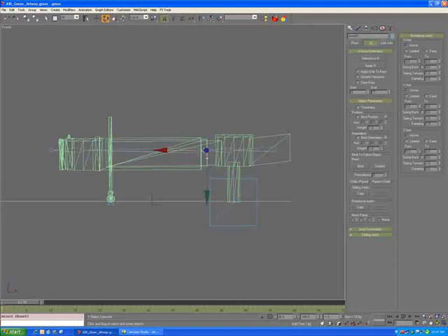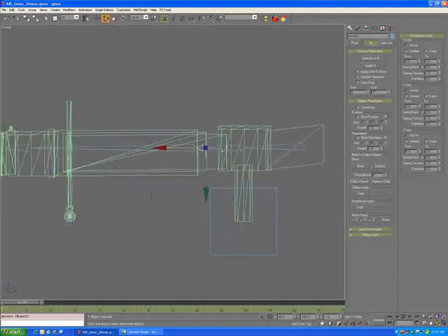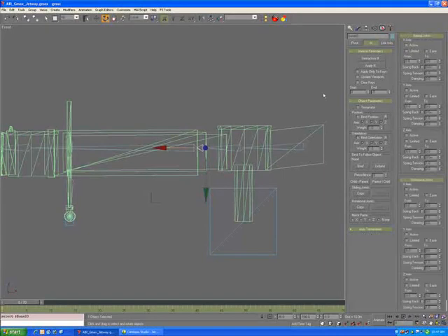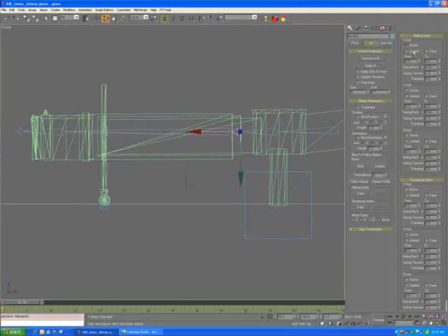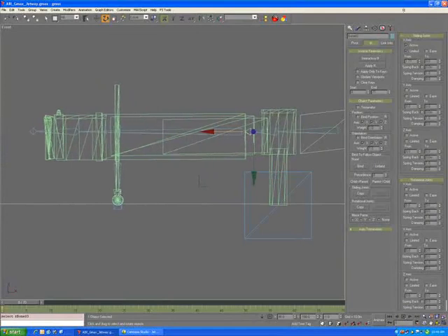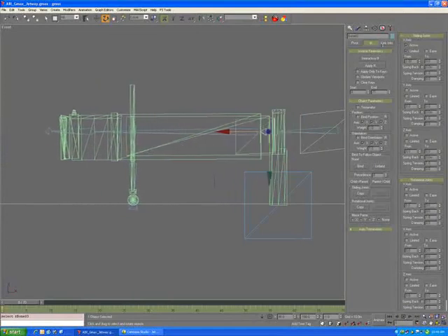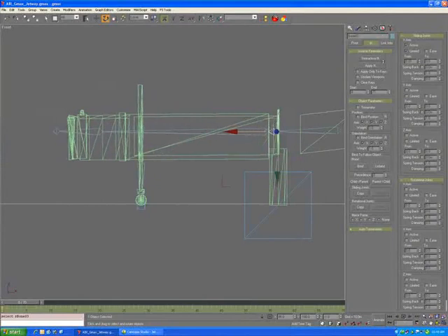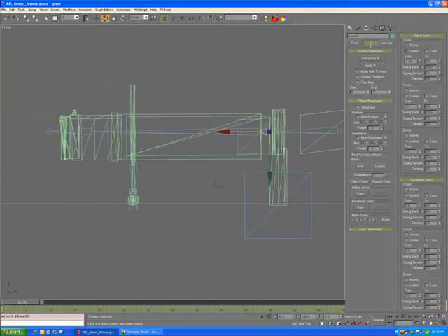So the next joint, and this is where unfortunately bones in Max and Gmax get really hokey, is when you have sliding joints on bones. You kind of have to guess. It's really, unfortunately, very problematic. And you will see. So the first thing we'll do is turn off the rotational joints, because we don't want these to rotate at all. But we do want them to slide along the x-axis. So we'll turn that on, active and limited, and here's where you see where things will get crazy. When you test your sliding joints with skinned meshes in bones, they fall apart, as you can see. However, this doesn't affect your mesh in the long run.